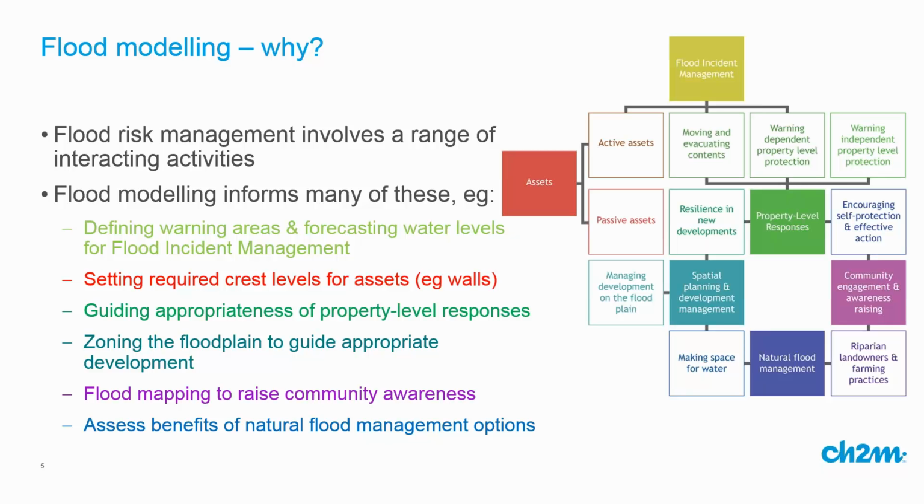Talking about flood defence assets, within the appraisal and design phase of assets, it can be used to help set the crest levels, for example, for a flood defence wall, or for undertaking an appraisal to work out the damages as they are today, and then how they would change with different types of options implemented, working out what's the best spend of the money. Property level responses, it can help guide property level responses to the most appropriate type of response depending on the depths of water which the modelling can predict, for example.